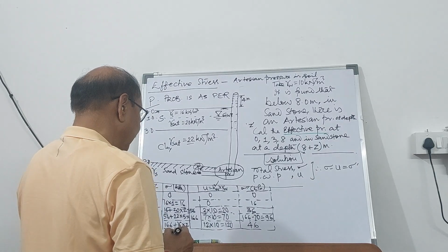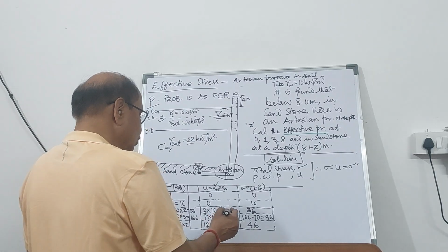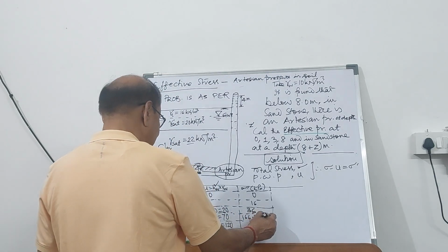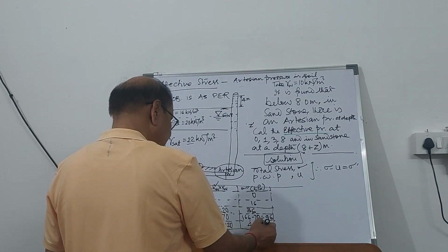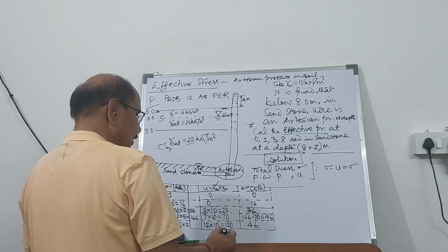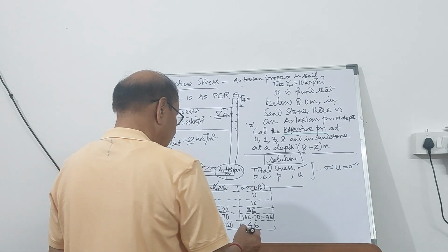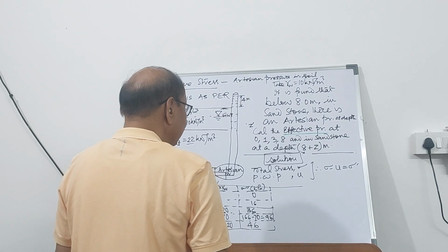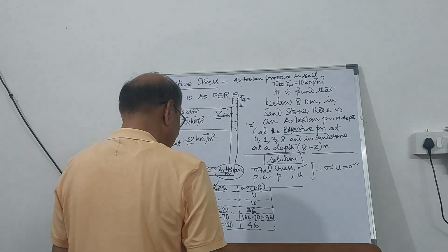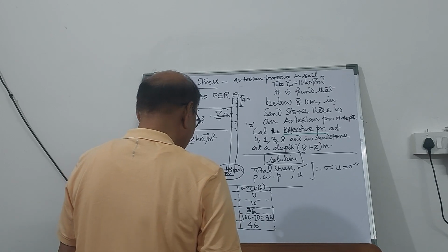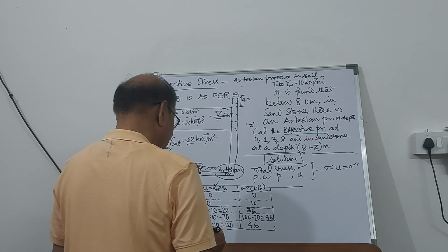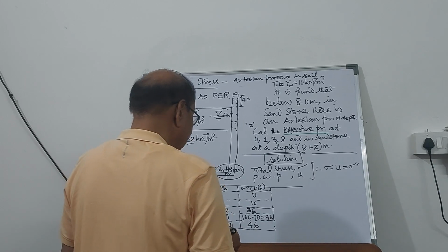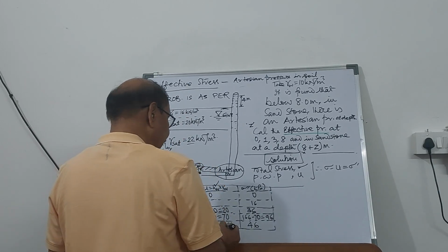So due to pore water pressure, the effective pressure reduces considerably to 46 kilopascal. It was 96 at 8 and just below, because of the increase in Artesian pressure. So this pressure has gone down. So effective pressure is going to be quite less, which you can see. Just below that, the pressure moves up by 50.